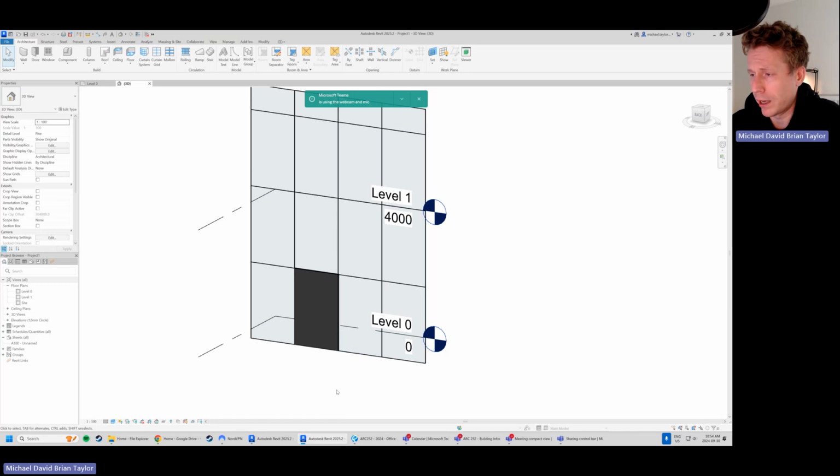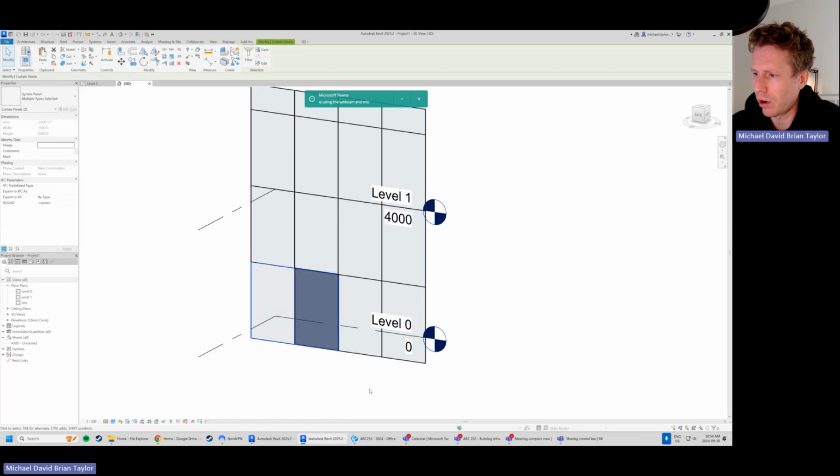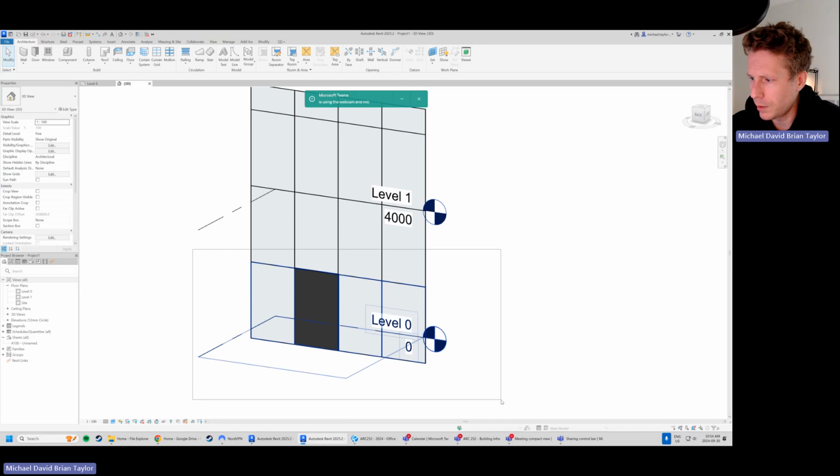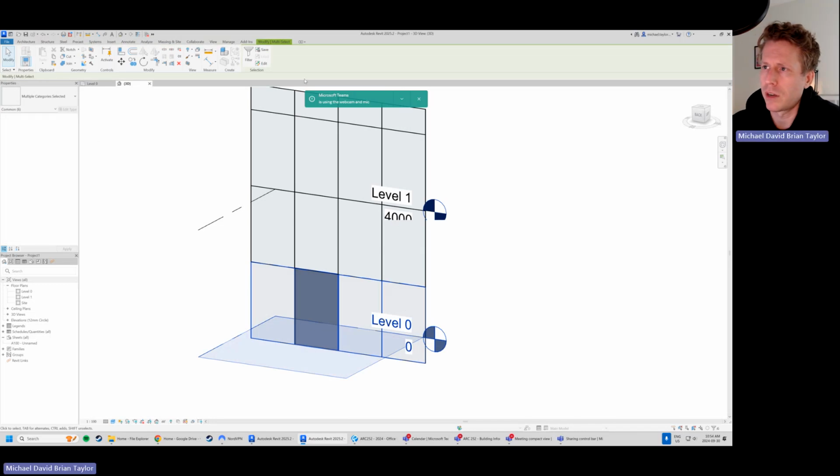This can be really helpful, again, when we're doing spandrel panels across things like slabs in our building. For the Best in Town example, we don't need this, but I just wanted to show you the tool itself. So a simple way to get this back, if we want this to be all glazed, is to just come across. If I select all of these panels, now actually I've got multiple things selected. I happen to also select my levels.